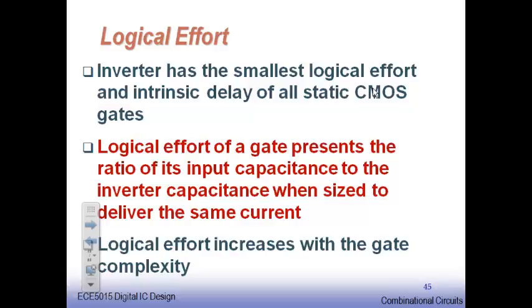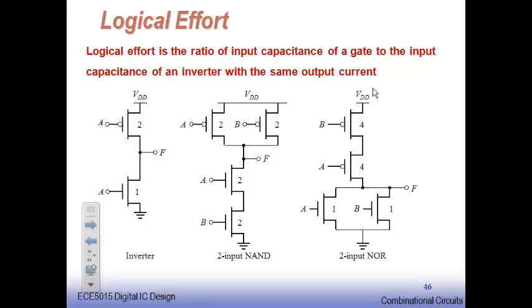An inverter with twice the width for PMOS, 1 time the width for NMOS, I am taking as the unit gate. And in comparison with our inverter, how big are my other gates going to be? Because I should have the delay derived only based on the G I calculate, and in turn the H I calculate, in addition to the fan out capacitance and the initial input capacitance I have as the C1. Right? Now, we will consider the logical effort calculation.